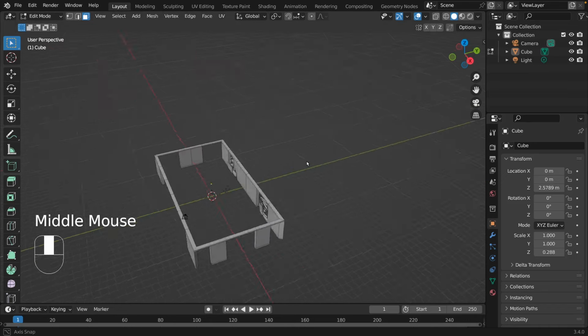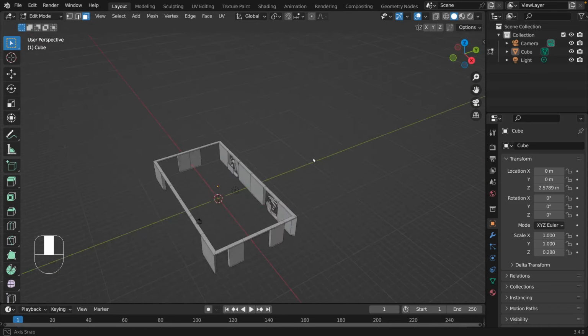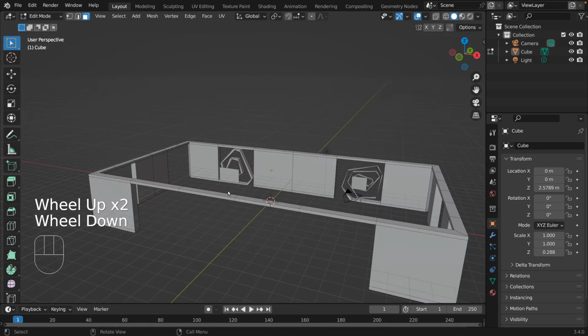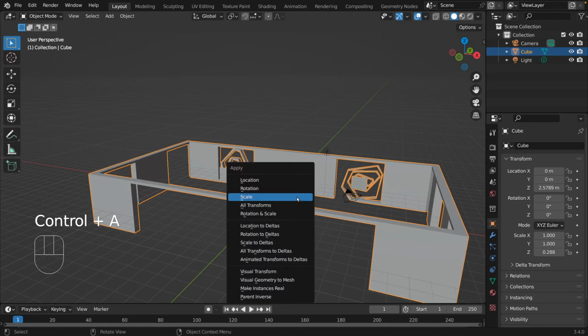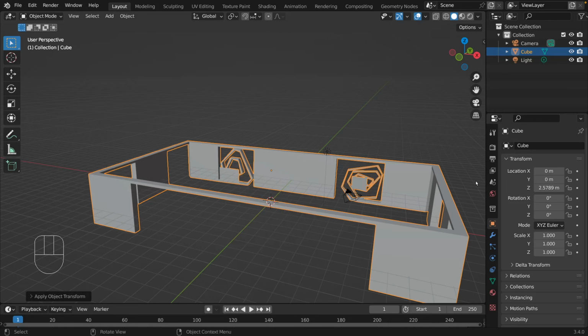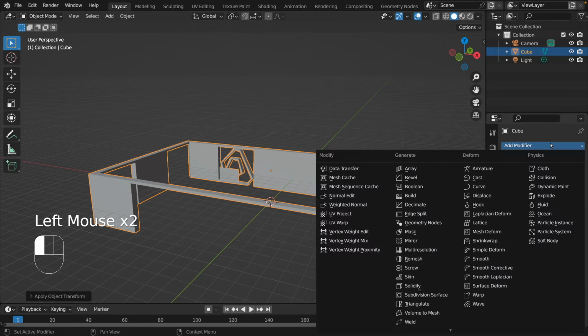And I think the result is already pretty good, but I sort of want this to be a cyberpunk and organic mechanic shape. So what I'm going to do is change the edges, and a good way to change the edges is to add a modifier. Okay, so first I'm going to apply the scale. So Control and A to apply the scale, and then I'm going to add a modifier. Click the wrench, and we get this.